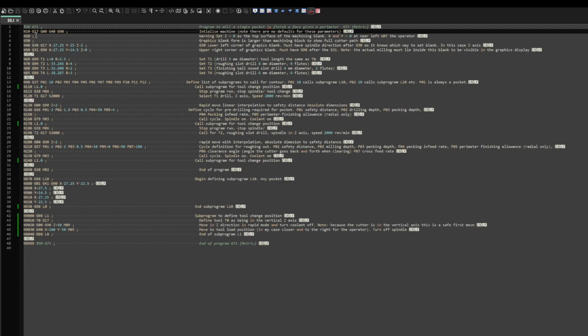This is, for the time being, go as fast as you can in every axis, and that is different on each axis on my machine, and it's in the machine parameters. You can limit it; I think my X and Y are 3,000 millimeters a minute, and the Z is heavier, so it can only do 2,000. G40 means don't compensate offsets for the tool, for the time being, and G90 is absolute dimensions.